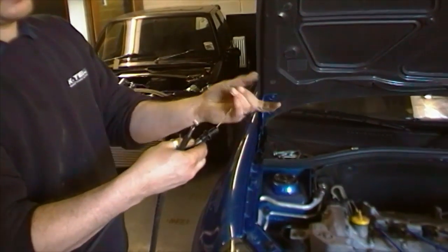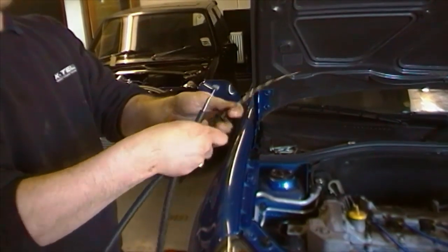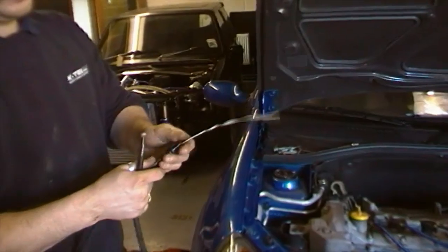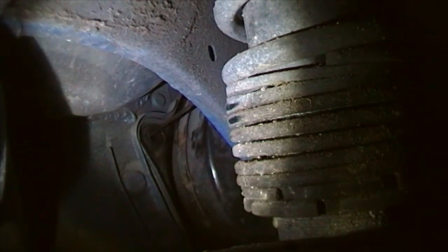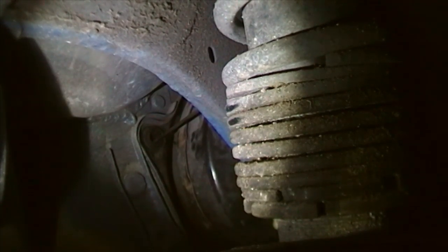It's difficult to get through, and then the outer sleeve sits in that, and that pushes home, and that allows your cable to not move through the bulkhead. Pull back the inner wheel arch to gain access to the bulkhead. You can see here the Allen key sticking through indicates where the hole is that you need to put the shouldered grommet and then the throttle cable guide.